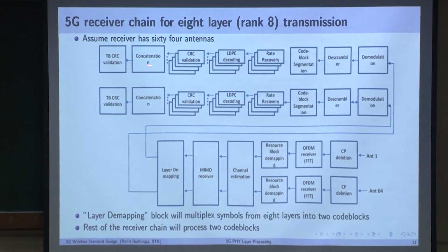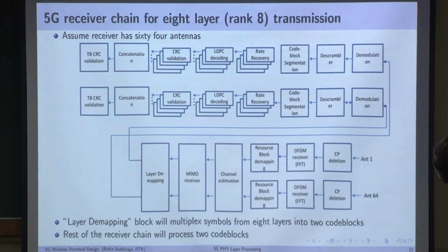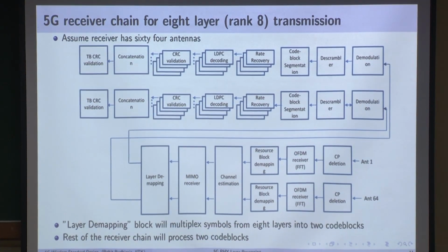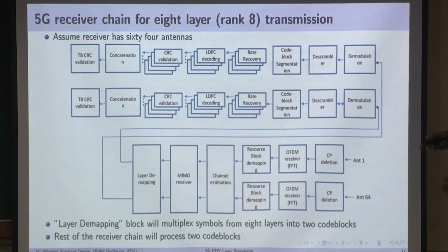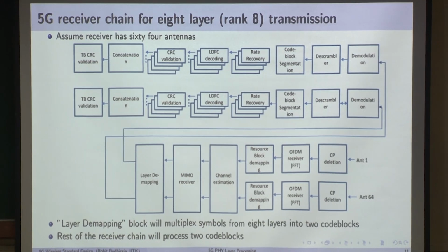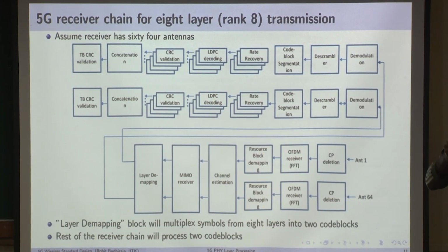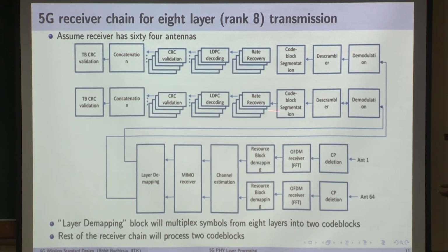If you run them sequentially, these blocks need to run at a higher clock, because this chain is waiting. So whether you want to design a system running at a higher clock, or a system wherein you can have 2 instantiations of these 2 receiver chains.